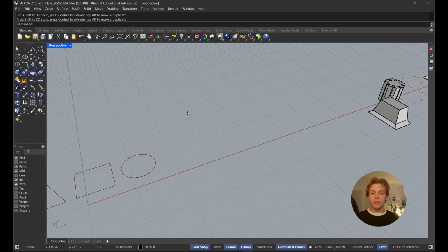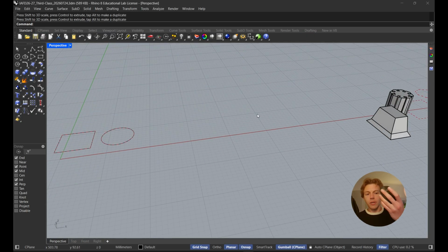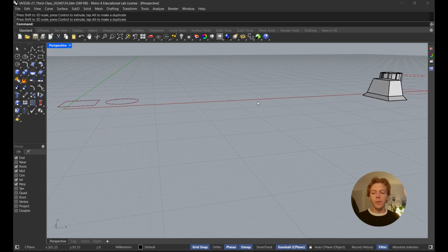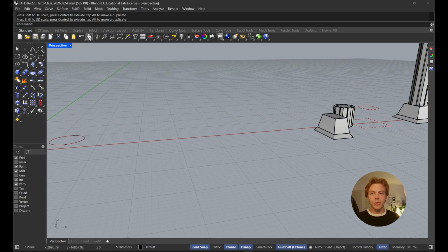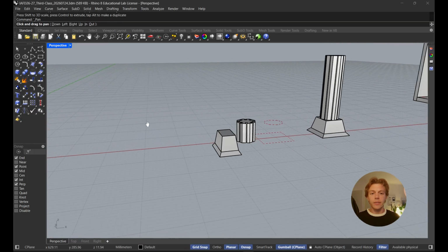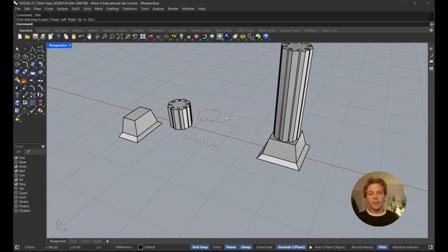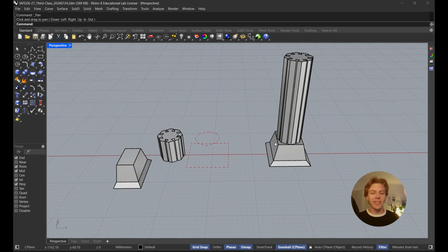Let's, again, if you don't remember, to drag around in the perspective view by right-clicking with your mouse, you are going to rotate the view. And by holding Shift and right-click, you're going to pan the view. You can also do it from this icon here and left-click. So here we have our Greek pillar or something along these lines.